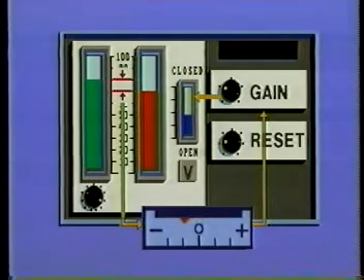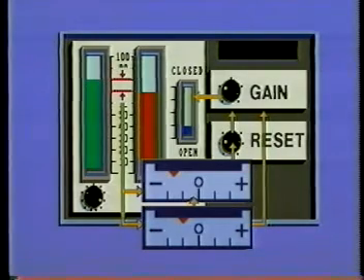Proportional action caused the valve to open in proportion to the temperature change. But in addition, the integral unit also responded to the error signal. The output of the controller slowly increased as long as the error signal was present. This increase in controller output caused by the combination of proportional and integral action caused additional valve opening. This allowed the temperature to return to the set point.